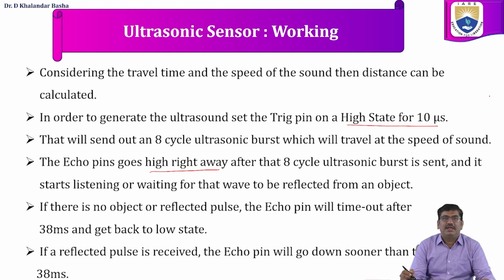So if there is no object or reflected pulse, the echo pin will time out after 38 milliseconds and go back to the low state. If the reflected pulse is received, the echo pin goes low sooner than those 38 milliseconds.